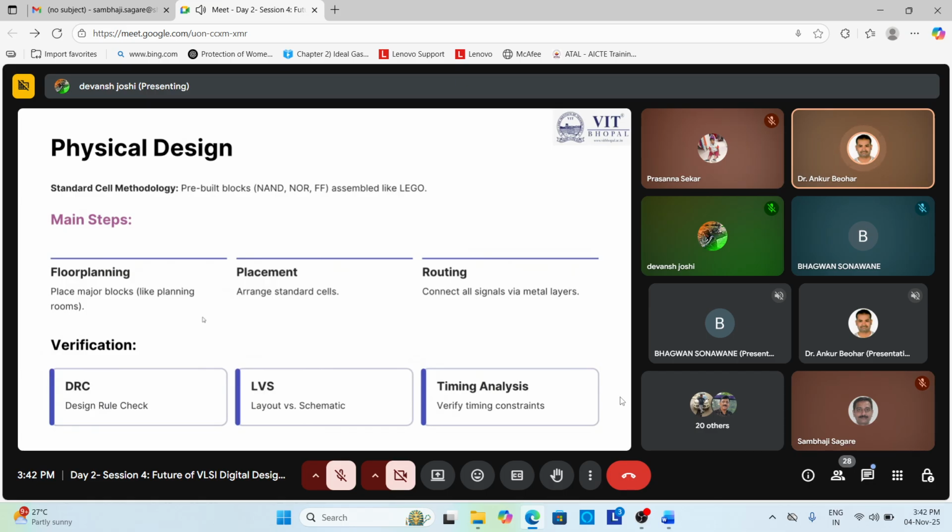So under DRC, we have verification of the physical layout. At that time we can also compare the design's layout against the set of rules provided by the foundry. Then violation reports can also be checked, covering traces and layer spacing, and component placement between different components on a board, along with enclosures. So all these we have about DRC.